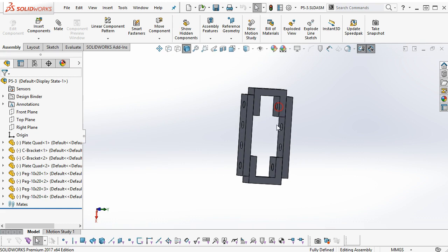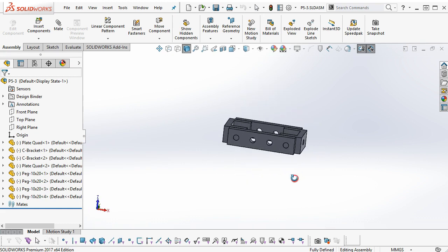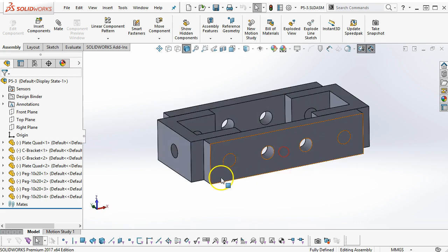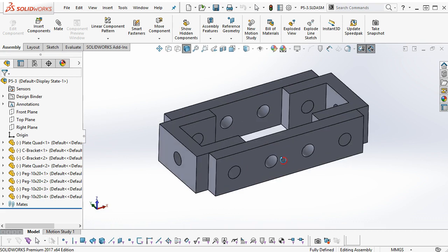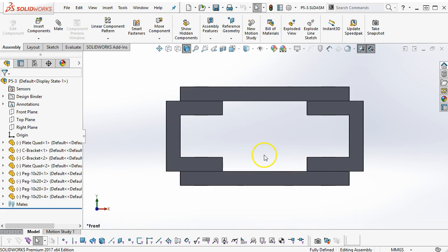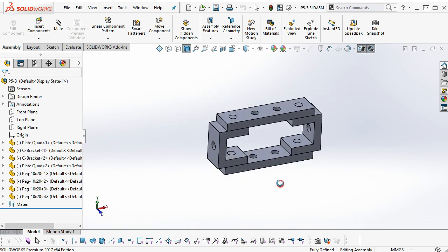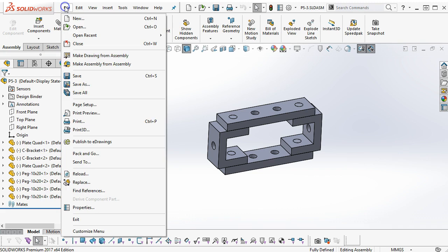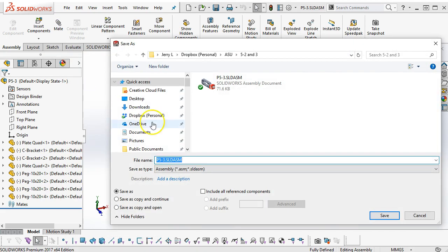The problem is going to be having the support structures in the middle to bridge this gap. So printing it on the side would be an option. I would have the items running this way, but I want to think in terms of where those boundary layers between each of the filament is going to separate to get some reasonably accurate loading. Right, so picking your position is fairly important.